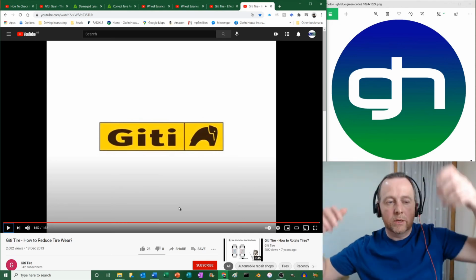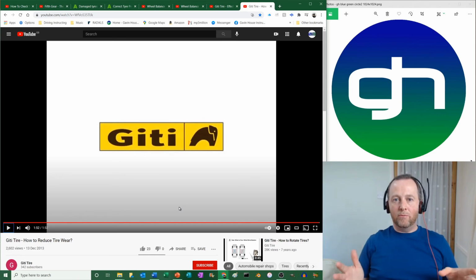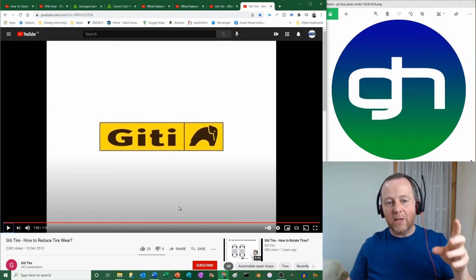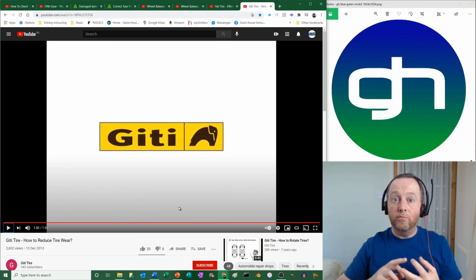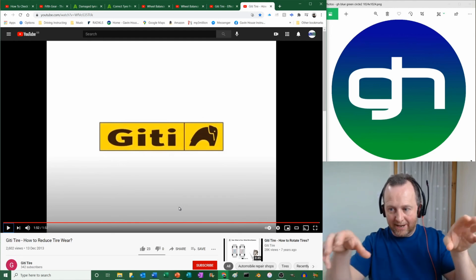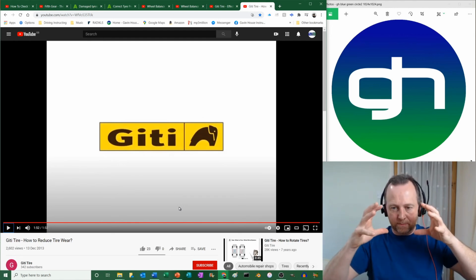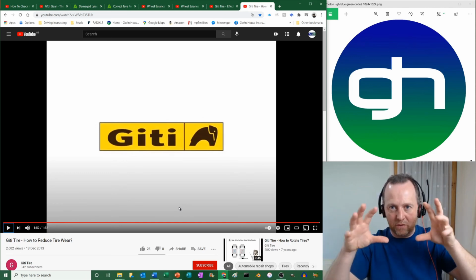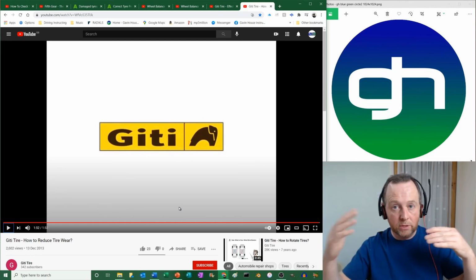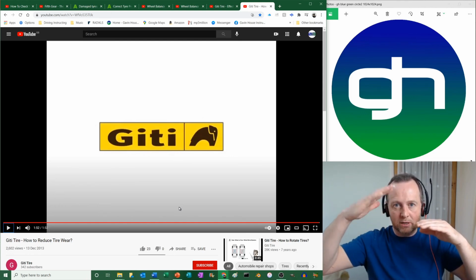There we go. So a little video about the tyres and how to control them. So wheel alignment is really, really important, as is the correct tyre, the correct inflation, all the rest of it. Something else that can affect the tyres is if your brakes are a bit grabby. So when you put your brakes on, if they're gripping the tyres, then your tyres will temporarily stop and skid down the road and then rotate again if your brakes aren't quite right. And also your suspension, which I'll come to on another video, which can cause the tyre to bounce.